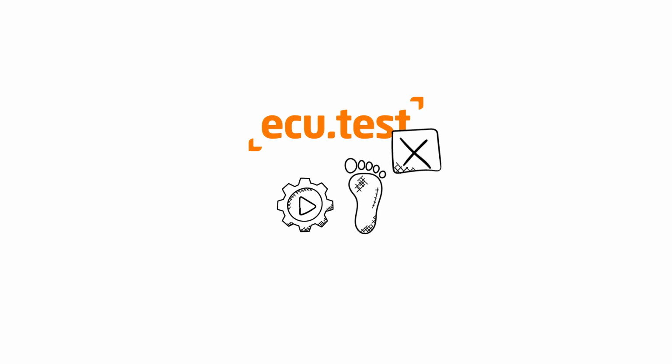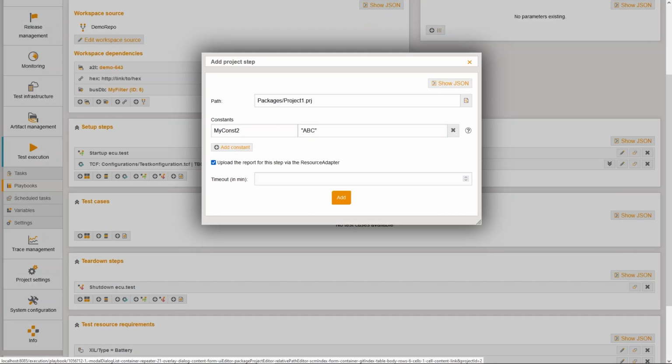There may be situations where, during the execution of a project step, ECU-TEST hangs up and the execution never gets finished. This is a really bad situation because your test resource may be blocked for a long time until you realize the problem. For this, you can specify a timeout at the ECU-TEST project step. When the timeout is exceeded, this step will be aborted and the execution will continue with the next playbook step.